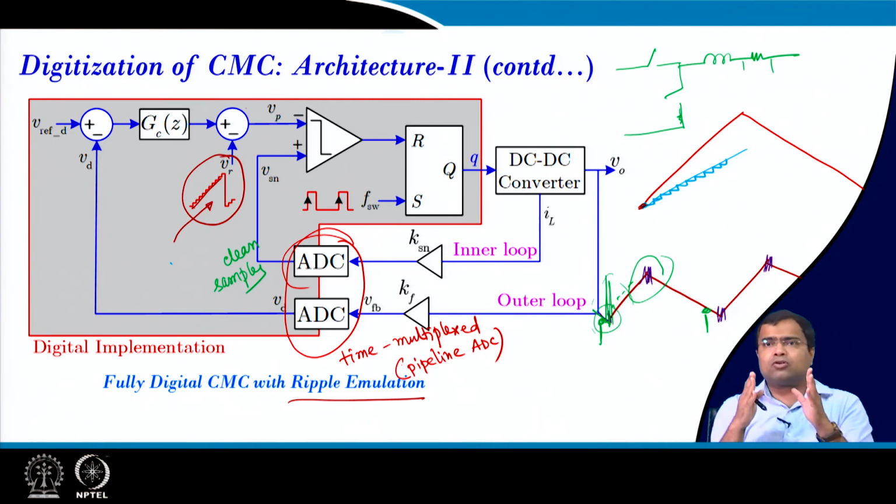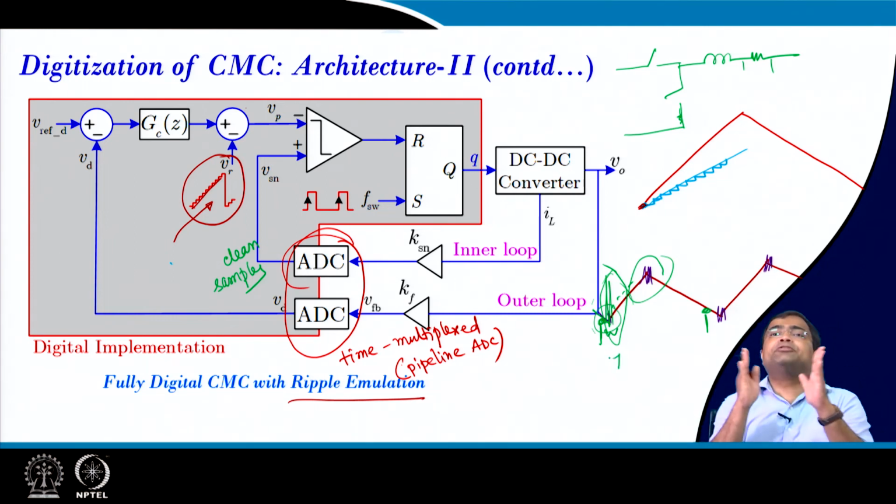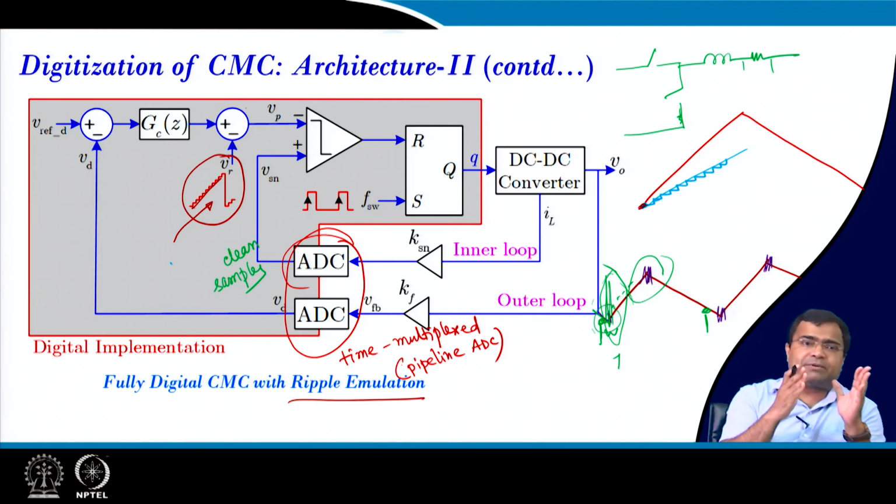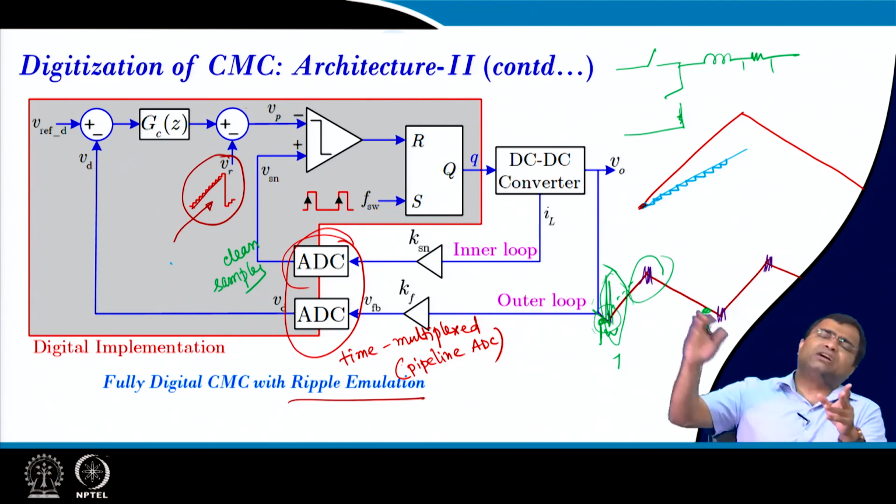So, in analog control, people use something like blanking, that means they do not take any action for a certain on-time duration, then only they compare. That actually limits the effective duty ratio operation. That means you cannot achieve a very low duty ratio operation due to this blanking mechanism. So a duty ratio below 10% or 5% will be 0, and it will start from 5% to the full swing.